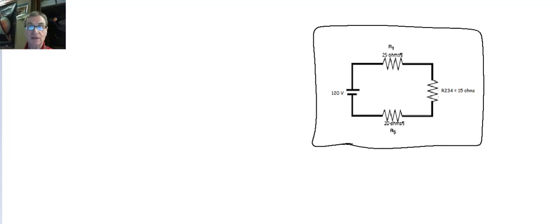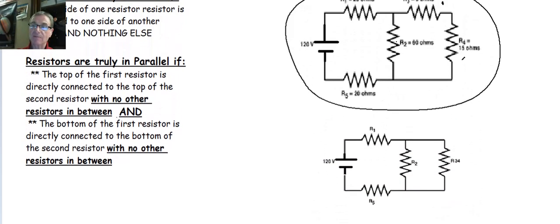Once we have this circuit, we can find out what the total current is in the circuit, I total. The total voltage of the circuit, which we know to be 120 volts right here, the total resistance of the circuit, and then we can take the information that we have and work backwards and backfill in information. Okay, so that's how we analyze a combination circuit.